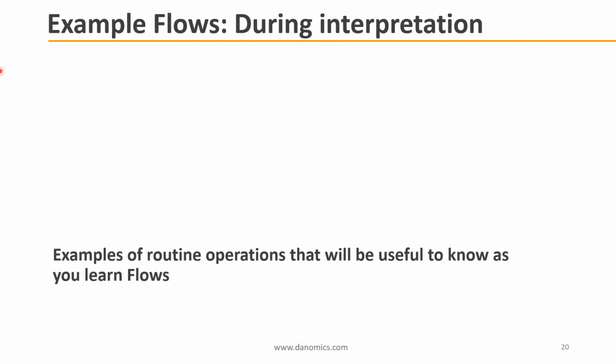Okay, I know I've said that you'll predominantly use flows either before or after your interpretation. There are some times when you may use a flow during the interpretation, and predominantly the use case for that would be to generate well lists. So let's say, for example, you only wanted to work on the wells that are going to affect calculations such as porosity or hydrocarbon pore volume. You could use flows to get out a list of those wells.